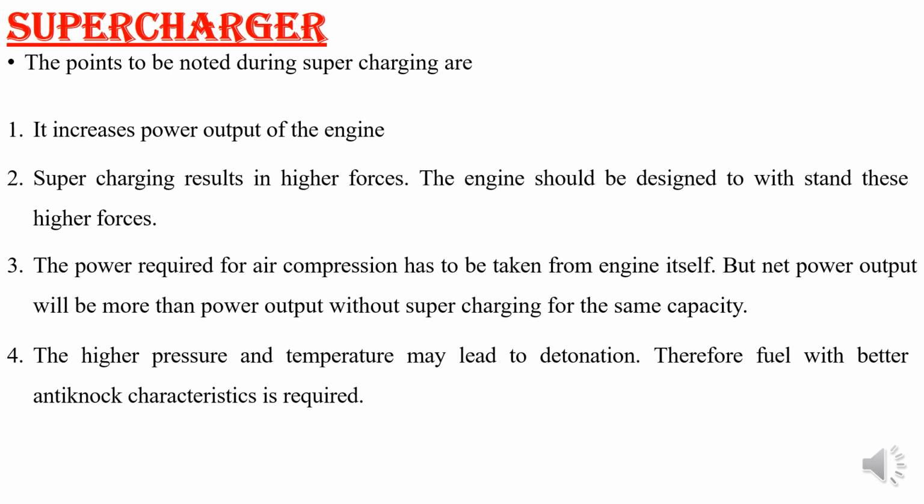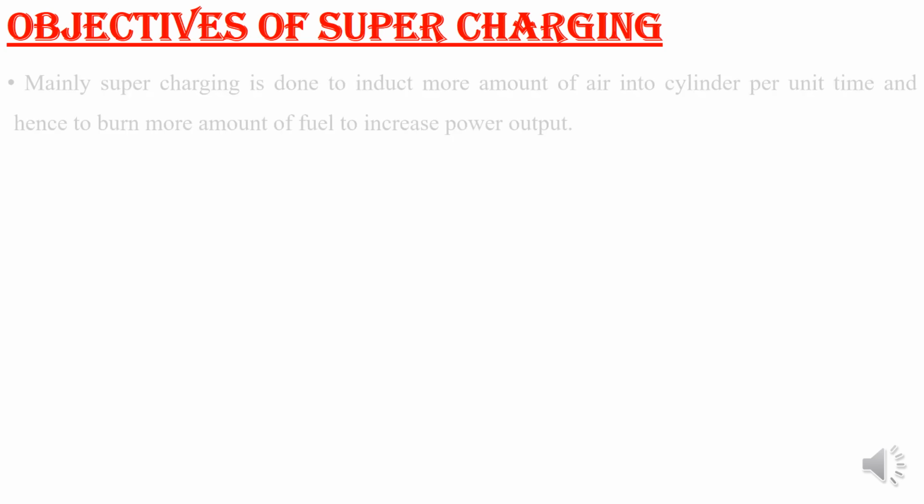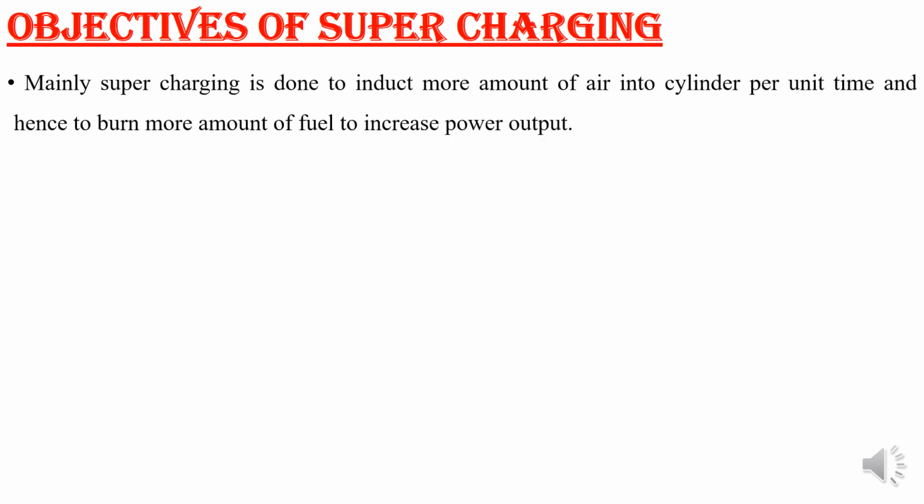So now we will go for the objectives of the supercharger. Supercharging is to be done so that more oxygen or more air goes inside the cylinder per unit time, and so more fuel can be burned so that power output can be increased.